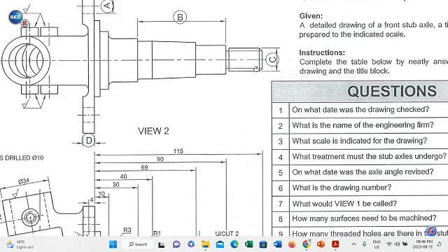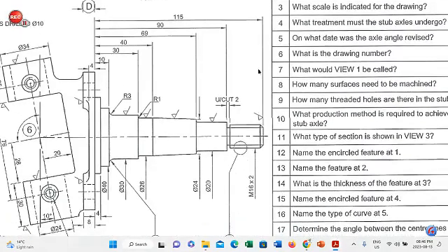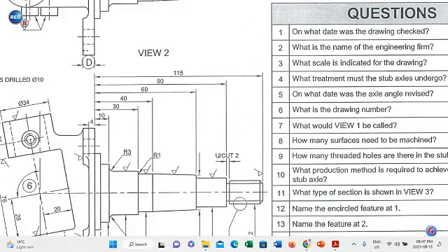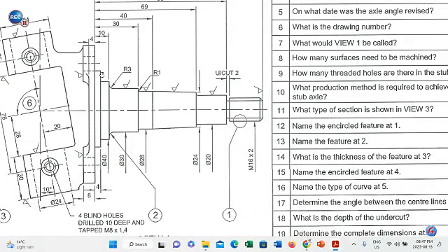C refers to the threaded part here. If you scroll down to your front view, you will find that this refers to that measurement here, which is an M16. And the 2 millimeters would be the 2 threaded parts that you will see here. So your answer would be M16. If you look at the width of D, you will have to scroll down and find that particular answer right here, which is 8 millimeters.